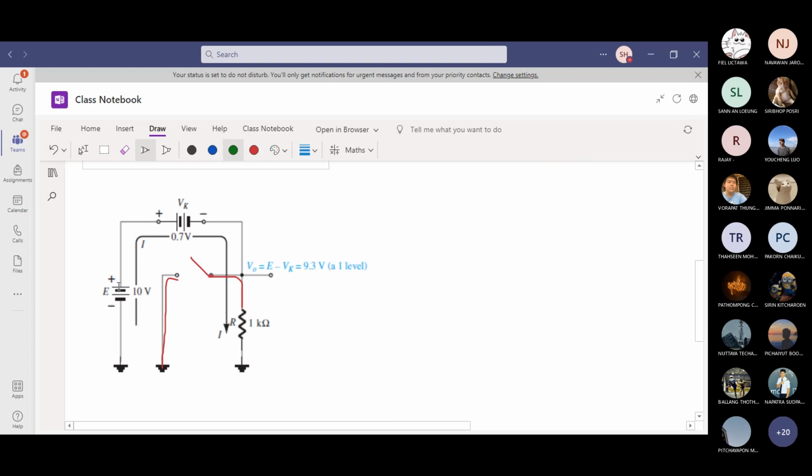The first diode, meanwhile, you gave a plus 10 volts, so we can draw a battery symbol, plus here. The minus is the ground of the battery, and the rest is connected to the rest of the circuit. So the outer loop is active. Now you want to put a probe. VO is the voltage drop from beginning all the way to here. 10 minus VK.